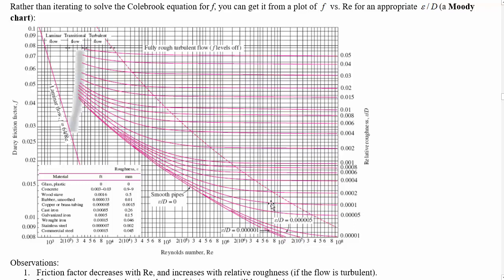And that tells you, if we go over and read to the left, trying not to lose track across the legend, it looks like we end up right here, which is a Darcy friction factor corresponding to 0.01, 0.02, 0.03, well, no, not quite, because these divisions here are counting up smaller amounts.